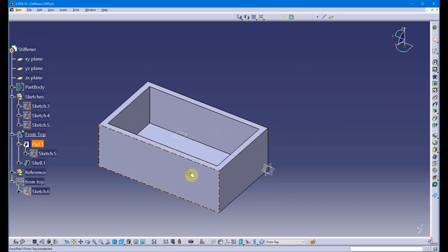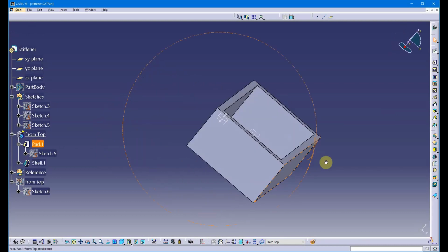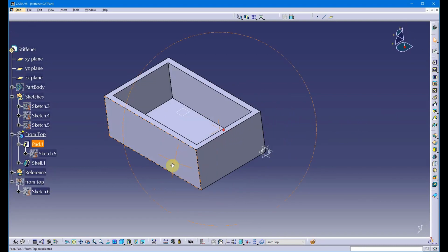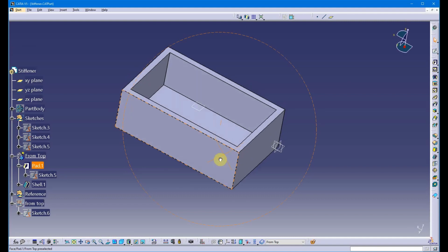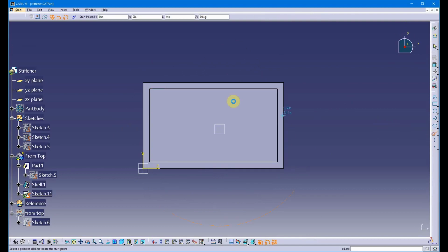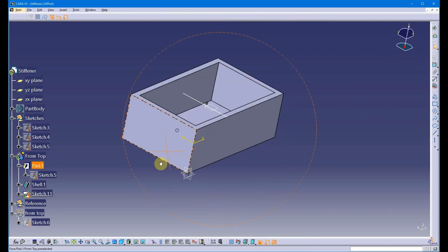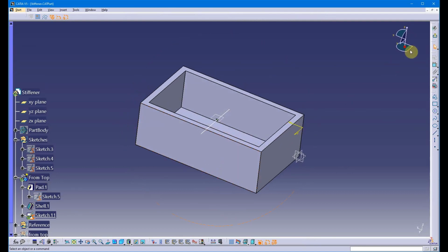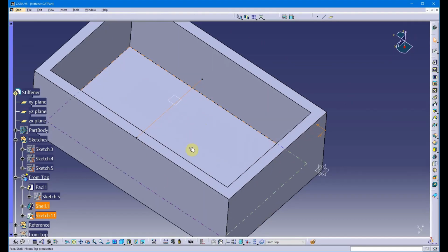If I were to take this little area here and create a sketch, and notice I've got a reference plane there, an offset reference plane in a part, and I keep this sketch open, then an open sketch such as this requires, if I wanted to do it as a pad, a thin wall, or the thick option.